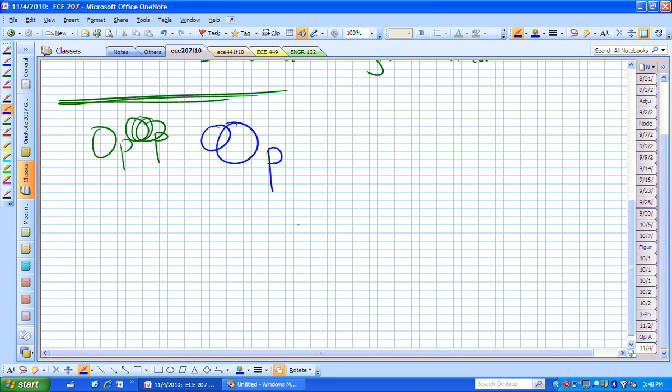In other words, we're feeding back a signal that is moving opposite to V sub x. So we have V sub x right there at that inverting node, and we're feeding something back that's going in the opposite direction. That's going to try to drive this V sub d to 0. It's going to try to force the inverting node towards the positive node, or to ground.